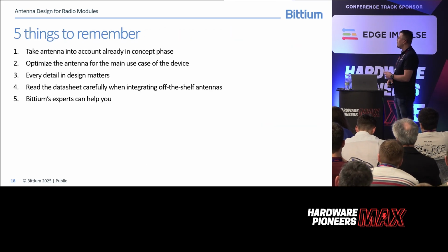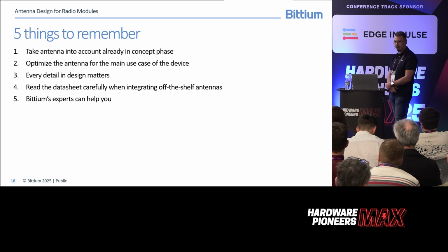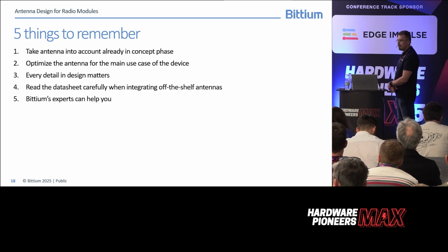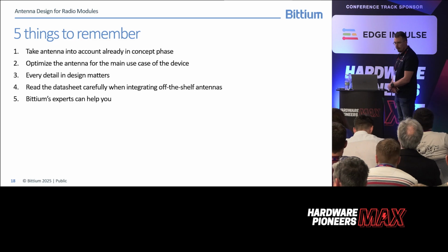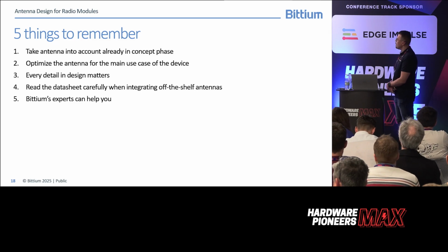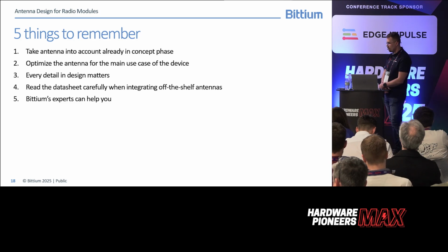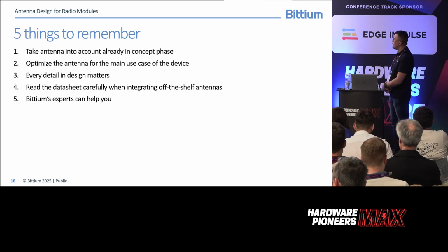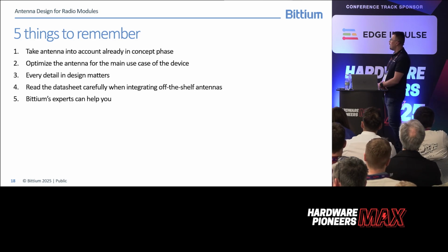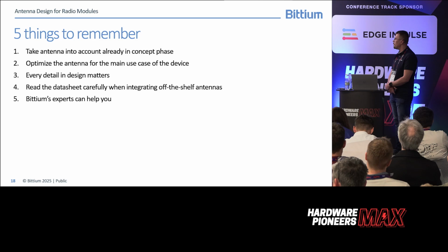Okay, and then five things to remember. Take the antenna into account already in the concepting phase, because that's when you have the possibility to affect the device's internal mechanics, for example, and then optimize the antenna for the main use case of the device.